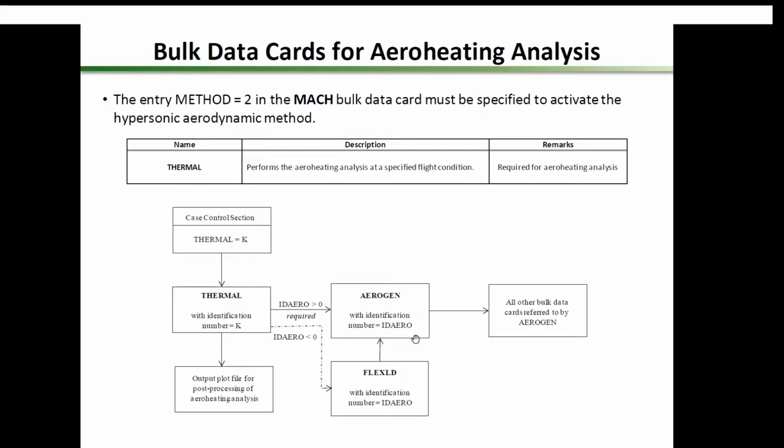And also you can replace the ZONAIR computed aerodynamic solution by a CFD solution, using the IMPCFD or IMPCFD1 card, to replace the ZONAIR computed inviscid aerodynamic result.